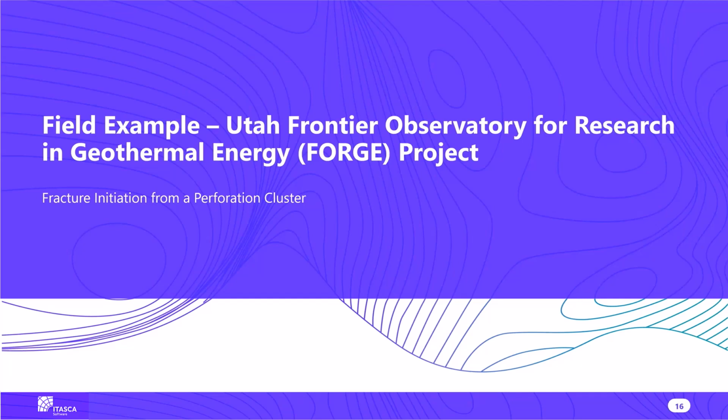So the first problem, we focus on modeling of fracture initiation from a perforation cluster, and this is a very important problem because the fracture geometry and its tortuosity in the near field of the well and perforation is very important because it affects the pressure drops and pressures required to propagate the hydraulic fracture, and even more importantly, the pressure required to circulate the fluid, let's say during the production phase, and also it affects how the proppant is transported and placed.